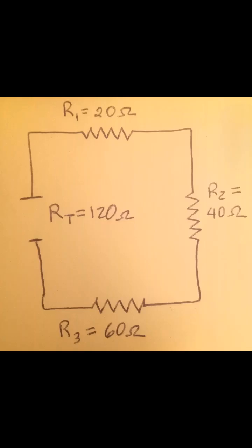Resistance in a series circuit. Total resistance in a series circuit is equal to the total circuit resistance combined. By adding the value of the individual resistors together, we find the total resistance of the circuit. See figure 6-3, where resistance total, or RT, equals resistance 1 plus resistance 2 plus resistance 3, and so on. Figure 6-3 consists of 20 ohm, 40 ohm, and 60 ohm resistors connected in series. The total resistance value for this circuit is 120 ohms.